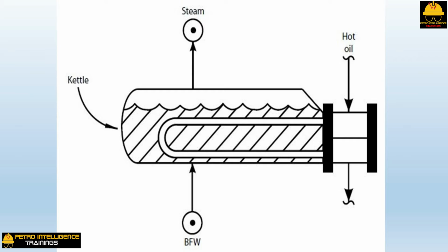If the BFW level is too high, this will cause water and silicate carryover into the evolved steam. This sort of carryover leads to more steam turbine vibration failures than any other cause. It's one of the major problems in the process industry.